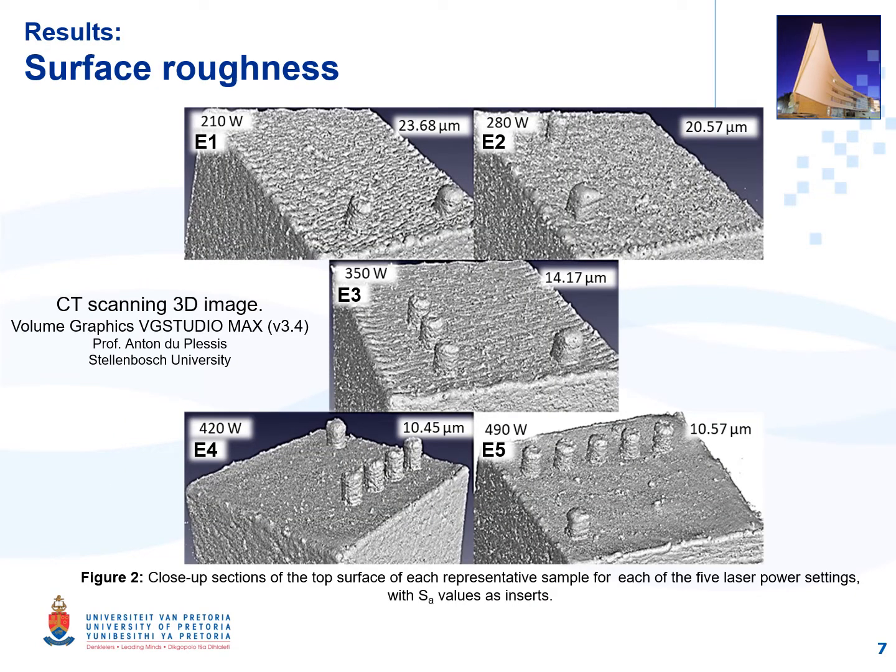The first tests were for surface roughness. As the top surface is the final layer of the laser powder bed fusion process, it is likely to be the most affected by the process parameters. The bottom surface was excluded as it was not representative of the parameters, due to the samples being manufactured on supports, which lead to an irregular surface.